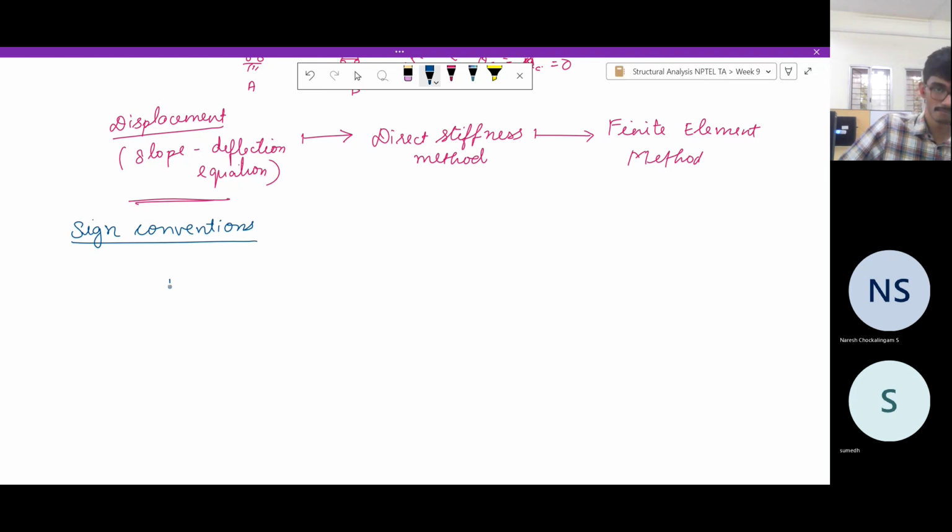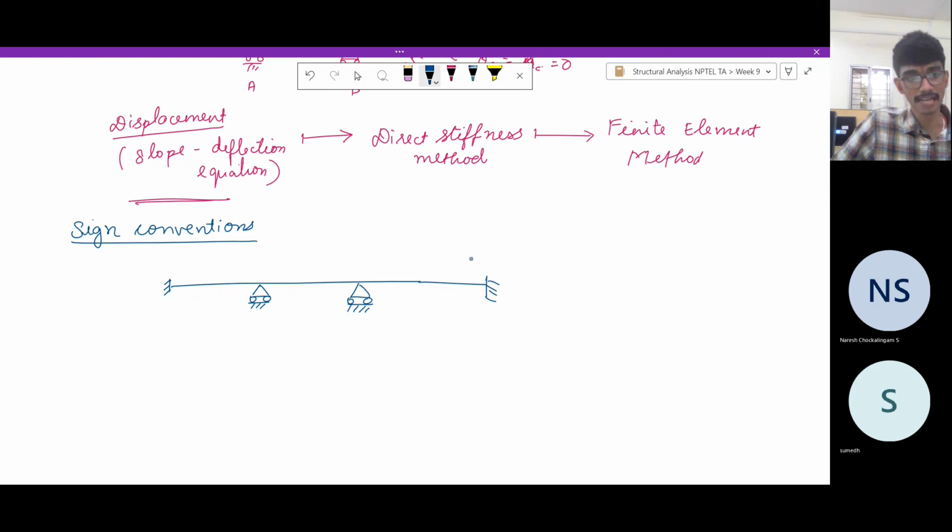We have a beam that continues over many spans and has something like this. So this is statically indeterminate to a very high degree. So what is ns for this? It is you can say 3 plus 1 plus 1, which is 5.